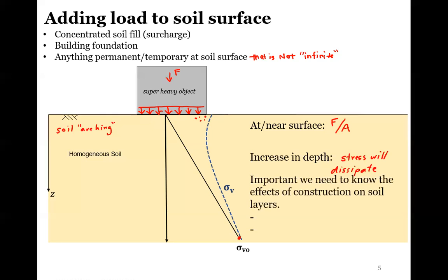So this is really important if we think about a geotechnical and a design aspect. Like we are adding a structure or something on the ground surface. We need to see how much that stress is going to change due to this loading, and at what depth will we not feel the effects of this structure anymore. It's super important for settlement analysis and also the strength of existing structures.